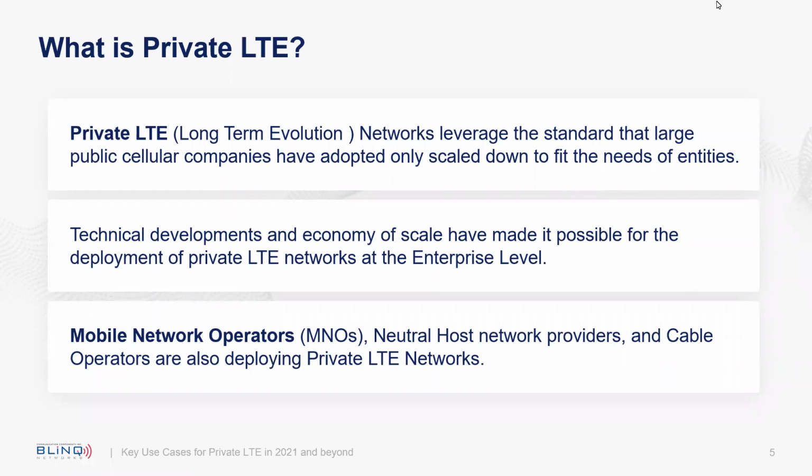In addition to that, spectrum sharing in the form of CBRS has been implemented by the FCC. It's now being deployed, literally hundreds of thousands of CBSDs throughout the US, and it allows PAL users, which are priority access license users, to operate alongside the general authorized access. Basically, you've got 150 megahertz, 70 megahertz of that is actually guaranteed for general availability, which is far greater than anything that they've had before.